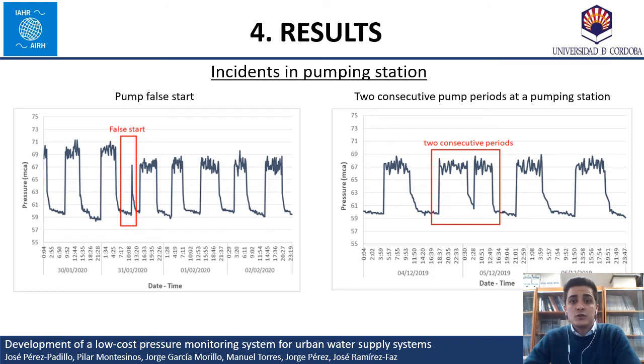As the figure on the left shows, false pump start events have been detected. This could cause long-term pump deterioration as well as unnecessary energy consumption. In this case, the cause of false starts was identified: a wrong signal from the tank level sensor that sent a start command to the pump control system. Another unusual operation was detected. The pump was running at 1 hour intervals. The situation was due to the existence of a leak in the distribution system. Therefore, the pump had to increase its frequency of operation to compensate for it.